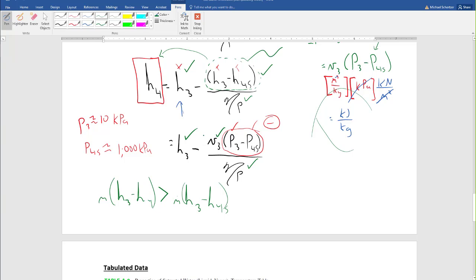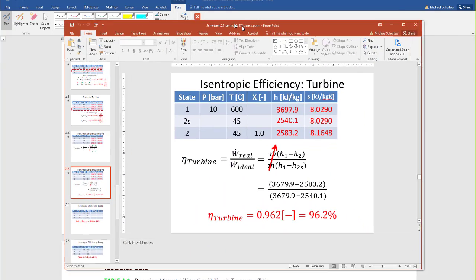And we can see that because here I'm dividing by something less than 1. So this delta is basically going to be the delta H for the real pump when we divide by this. So it's the delta H of the ideal pump divided by 0.9, right? So that's multiplying by like 1.11 or whatever it is, right? So here the delta is a little bit bigger, right? So here we would be satisfied that that's more or less correct, right?